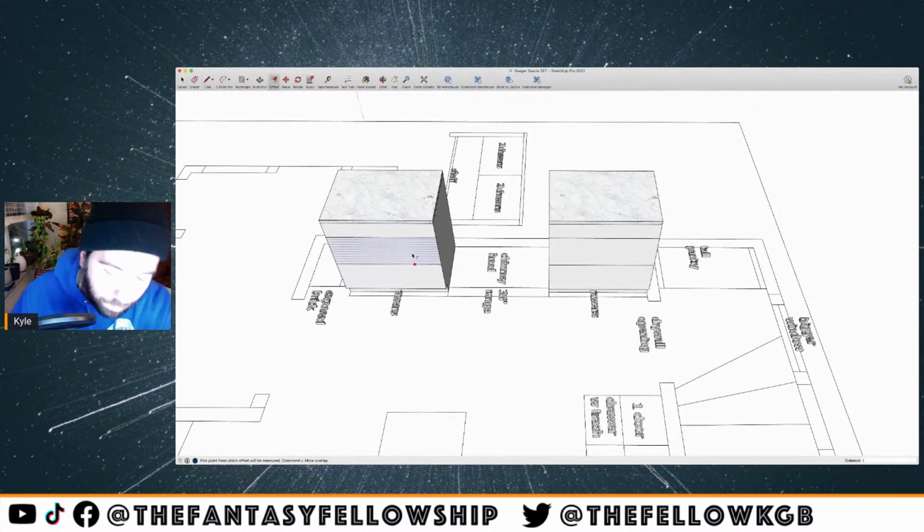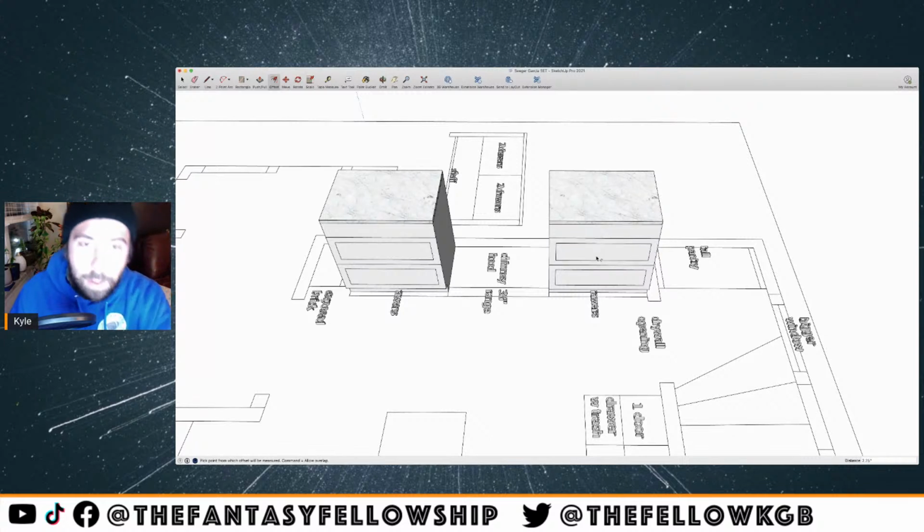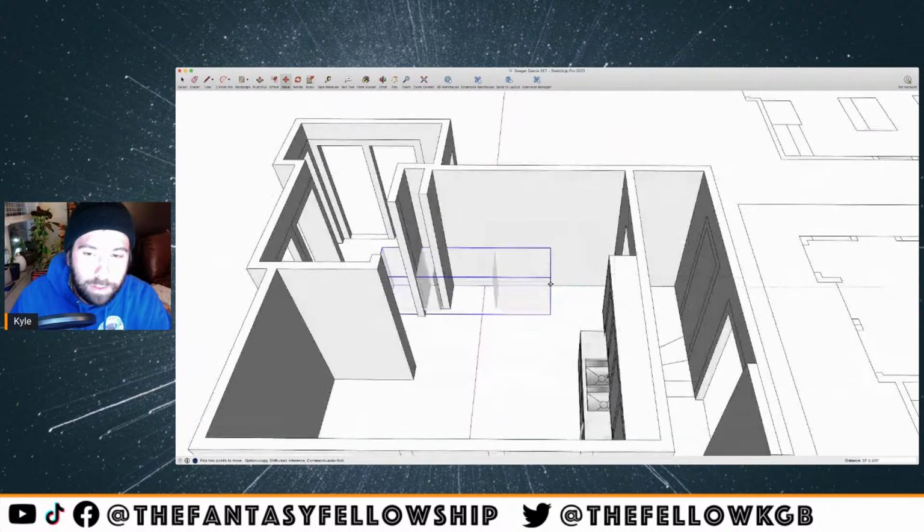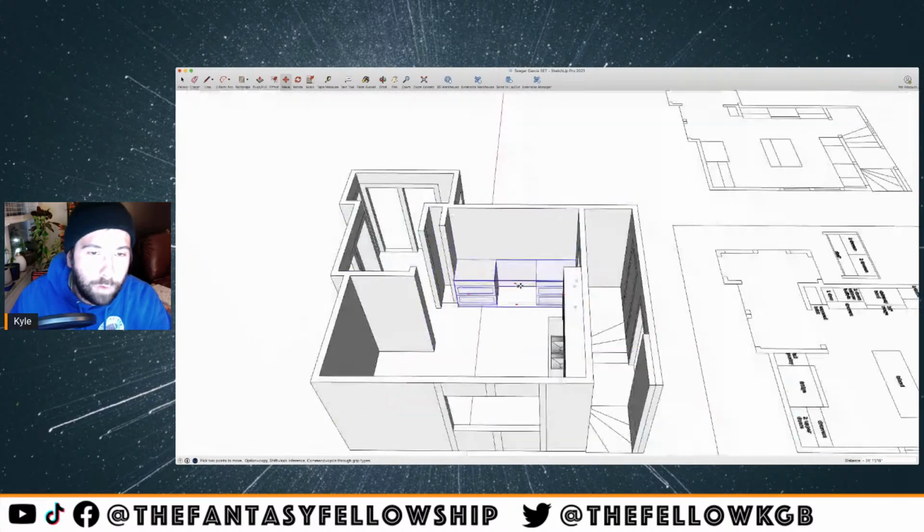And then from here, we will do our inset, 2¼ inches, and we'll get these drawers looking like drawers. And then again, on the top drawer, I don't usually do an inset looking panel there. I'm just going to make these guys a group. And let's go ahead and flip these over into the model here. And now we can start to see what our range wall is going to look like.